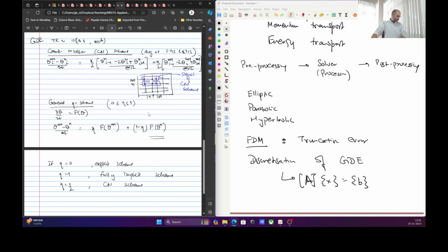And there's also a way to specify general theta schemes that we have talked about, and you will see in solvers, rather than saying backward time center space and schemes like this, they'll have a general theta scheme, or eta scheme, whatever. So you'll have to set a value of eta, and changing the value of eta will result in different kinds of schemes that you are using.